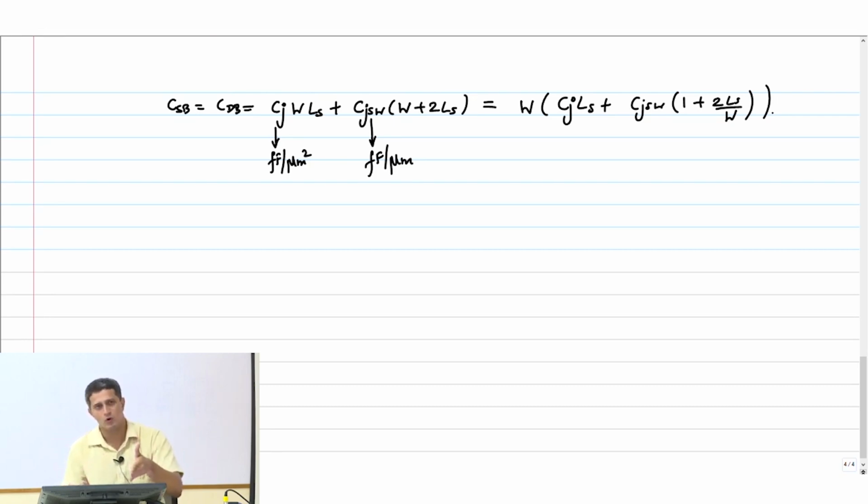Whatever I showed you now are the transistor's own capacitance. It's not any load capacitance. So they are called parasitic capacitances. So parasitic delay is to a first order independent of W, right? But of course, because I have a load guy coming in, it brings in some very interesting optimizations that I can do. We will look at all of that later on in this course.